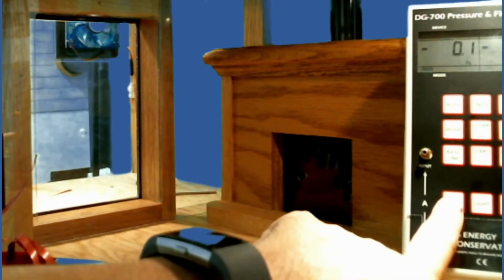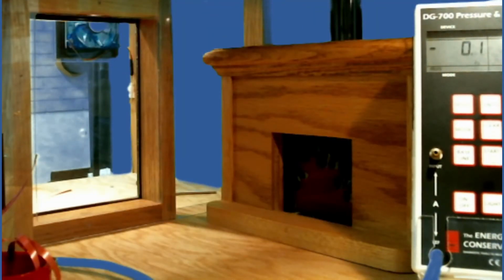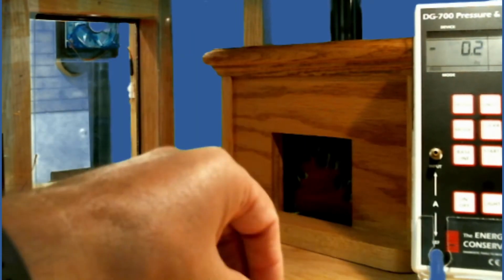And then in this case, you can't see what the buttons are here, but you would do a baseline, and do all the steps for that to set your baseline, depending on what manometer you have. Now, I've got this hose, and this hose, again, is going to the outside. So that's CAZ with reference to the outside.